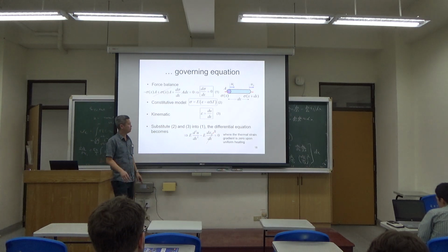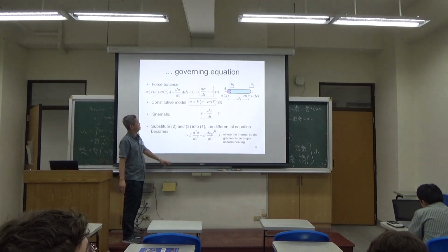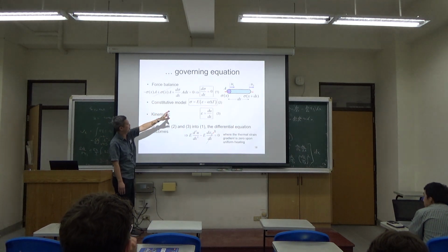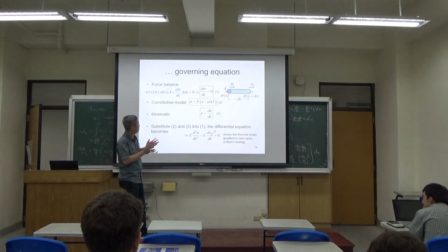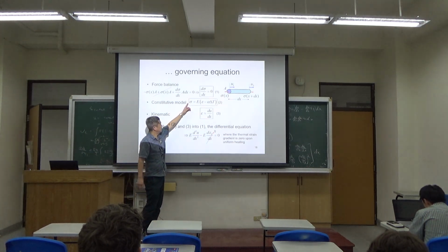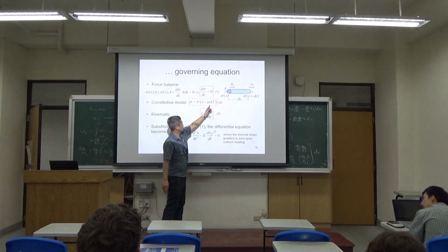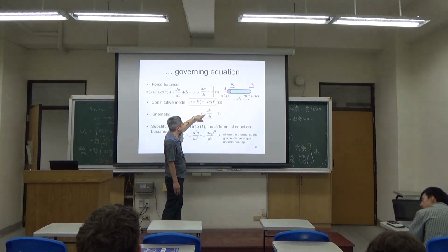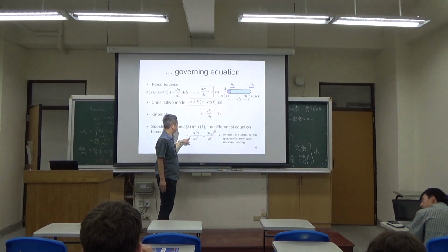So, how to write the Galerkin equation for the rod subjected to heating? To do so, you do the same force balance on one single element. You can find the stress change with space is 0. But this time round, the stress is equal to the net mechanical strain. So if you substitute the total strain, du/dx, then you are going to